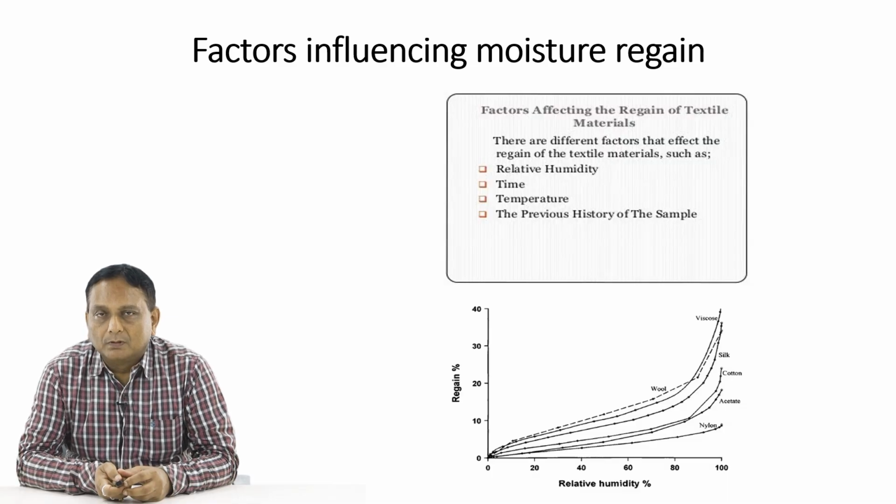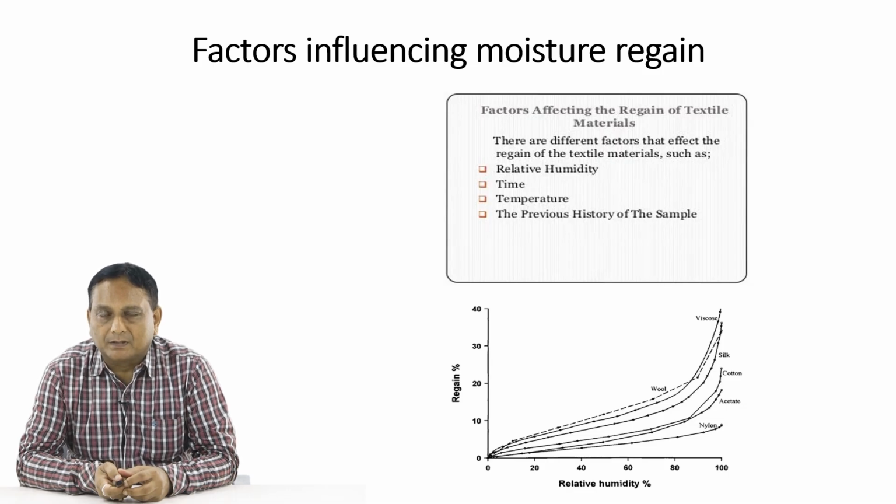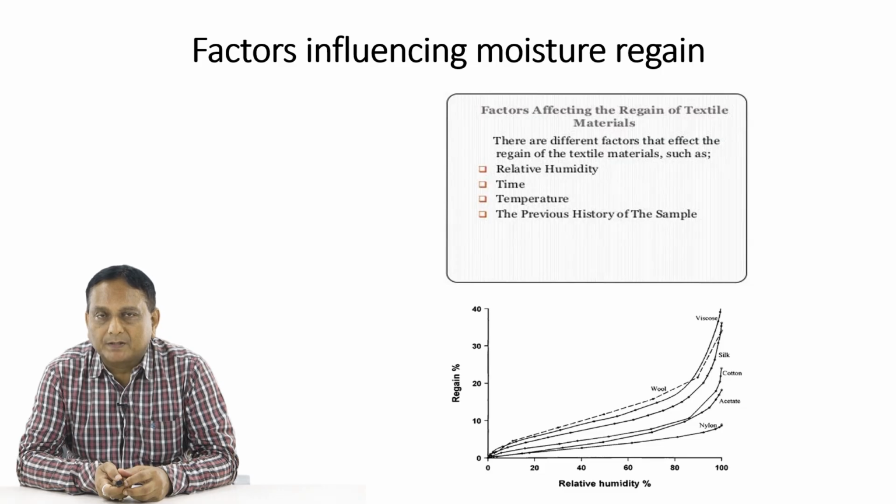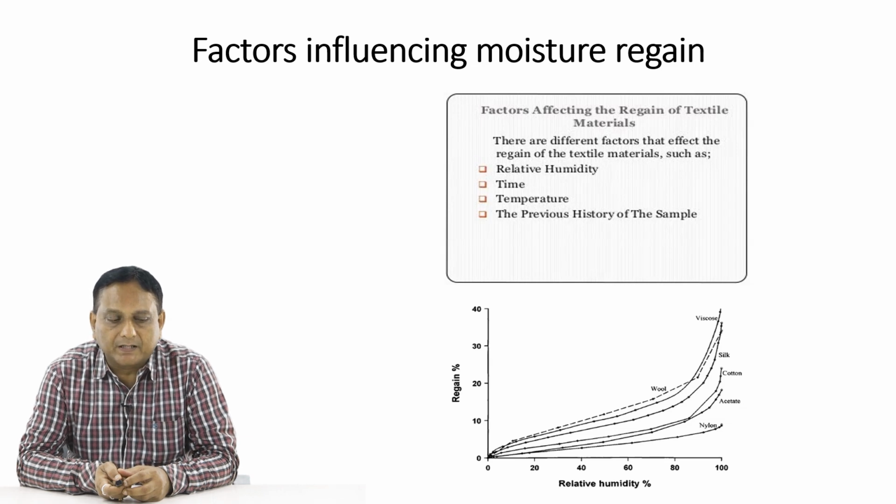Okay. So a lot of mechanical properties are related with this relative humidity and the moisture regain properties. So the same fiber will act differently in different relative humidity conditions. That is the reason in testing, when you are doing it in standard conditions, we are getting accurate results. But when such a fiber is tested at a higher humidity zone or at higher temperature, the stress strain curve varies. So this relative humidity and regain percentage are very, very important to control the properties of a textile fiber.